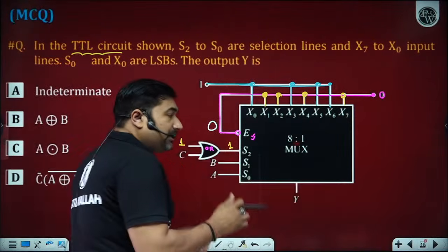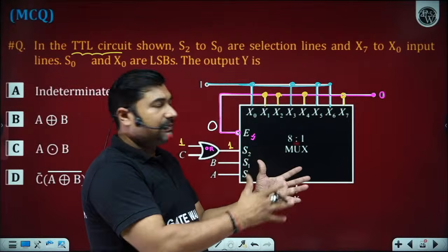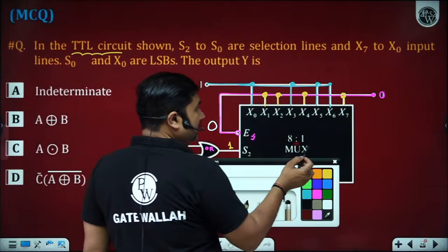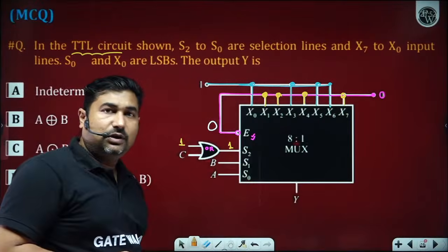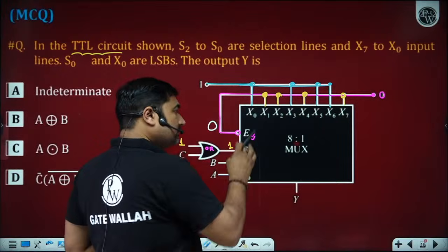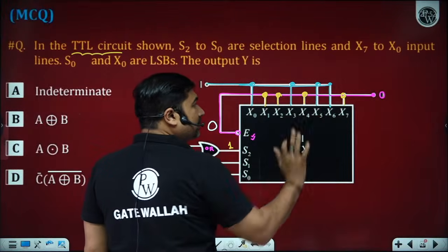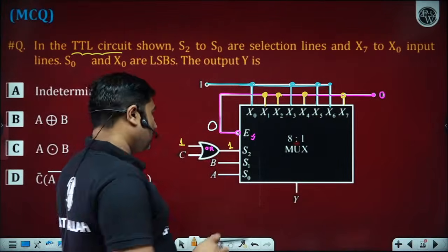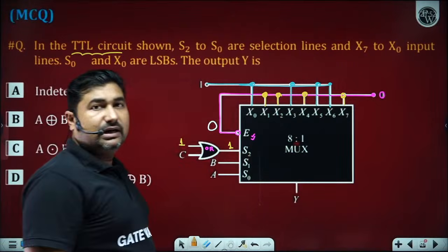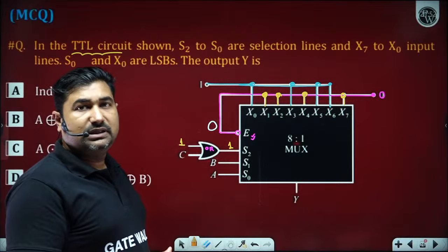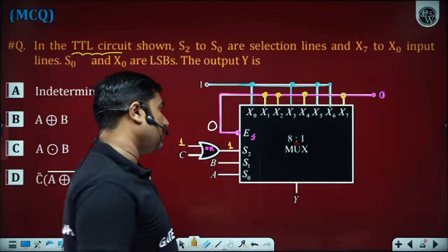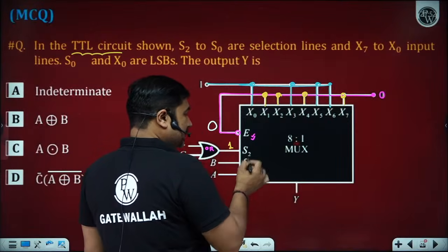How many of you able to understand the internal circuitry of the multiplexer? Because of the select line action, we know about the functions available here. Please observe, betaji. Enable is high, which means each of the input AND gates is enabled now. Depending upon the select input, one of the inputs is being transferred to the output. Now we have S2, S1 and S0.